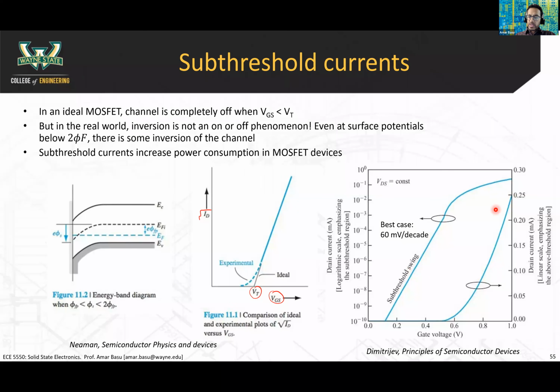If you're wondering what this blue line is, it shows the drain current plotted on a linear scale. On a linear scale, the IV characteristic looks like this. If you plot it on a log scale, this second blue line, you see that it looks like a line in the log scale like this. This means there's some sort of slope to this, and in the best case, that slope is 60 millivolts per decade.